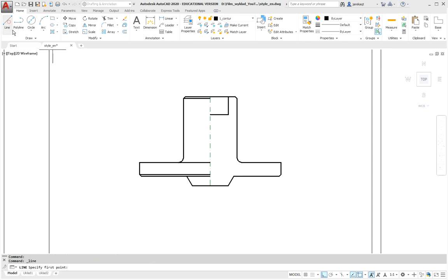In turn, we draw the thread 14, or again end point, because 14 is a simple number again. We leave, and we say 7 and perpendicularity. To draw this thread, the hole needed is drilled; for the M14 thread, 14 times 0.8 is needed. You can do it with such approximation that it will be 11.2. And 11.2 is hard to share a little, so you can draw a circle like this, 11.2, enter.